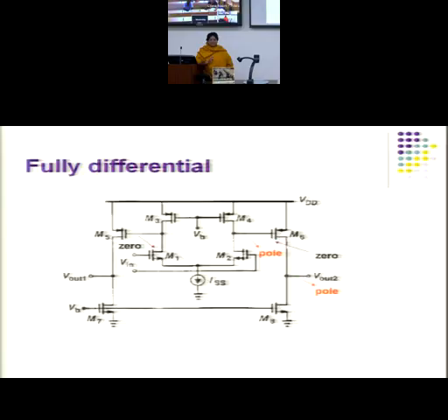So this is an ability that every analog designer should develop. And this aids in synthesis also, because this gives you a very good understanding about the circuit behavior. If I make a change at this particular node, how do the other nodes vary? How does the frequency response change? How does the swing change? How do the ranges change?